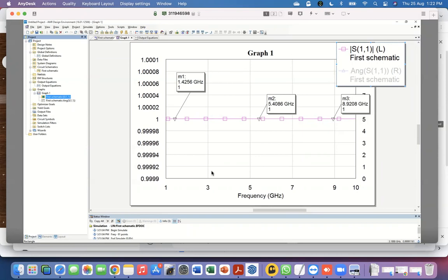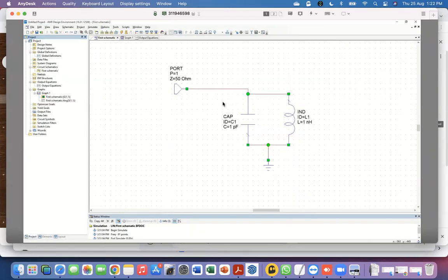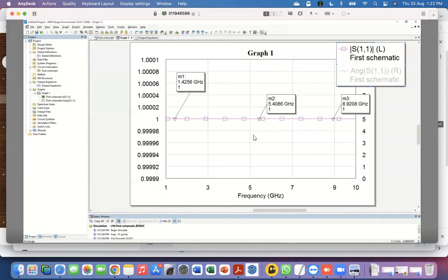So this again looks very strange and surprising. You are basically trying to measure a resonant circuit, but this quantity, magnitude as a function of frequency, is showing absolutely no information. Like, how do we know there is a resonant frequency, right? For this circuit, it's 1 over square root of LC over 2 pi. But this thing is showing absolutely nothing.